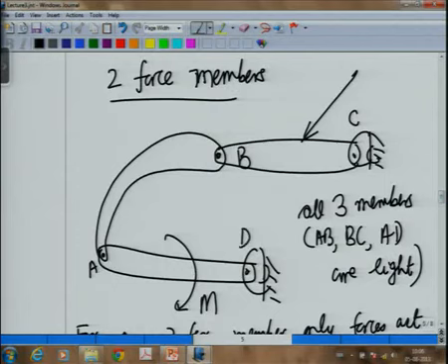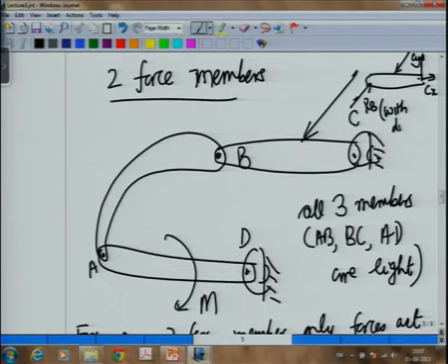Now, when you draw the free body diagram for BC, you will show unknown forces at C, you will show whatever force is acting. Now, what will happen to the force at B? It will be just a single unknown, because the force at B has to be along the line joining AB. So, therefore, when I draw the free body diagram of BC, I will show Cx, Cy, I will show this force, and this unknown force, which is RB with direction known.